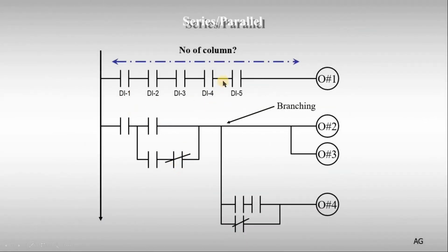So in this case, how many contacts you can have here, or how many columns or conditions? Again, it's based on the PLC brand and the PLC CPU. So in the same brand you can have multiple options here. Branching, which means you can branch from the rung. Each one of these we call a rung, and when you branch it, you can maybe have another additional condition or contacts in this area. Maybe you cannot. That depends on the PLC brand.